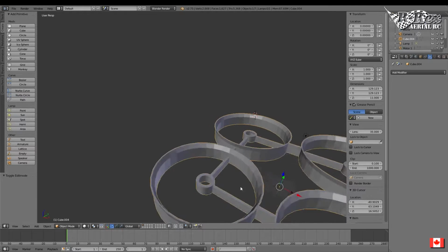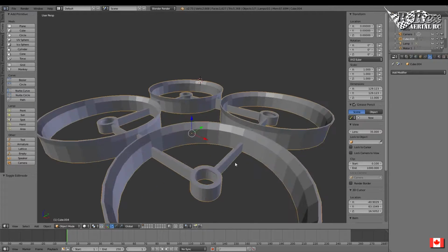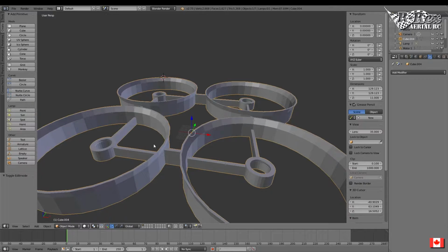Select my next one. Let's take Z to 13. Okay, so now I've added that for strength, but there's a lot of extra surface that you don't really need. What really adds the strength is the distance. So fiberglass guys will actually understand this. Anybody that does fiberglassing or carbon fiber, anything with resin, understands that the reason why there's more than one layer isn't to add structural strength in the fact that 2 is better than 1. It actually allows space for resin to sit in between the 2 layers, allowing the 2 layers to be spaced apart from each other. And that's what actually creates a very stiff, strong form. So the fact that we have surface all the way from the top to the bottom is rather unnecessary.